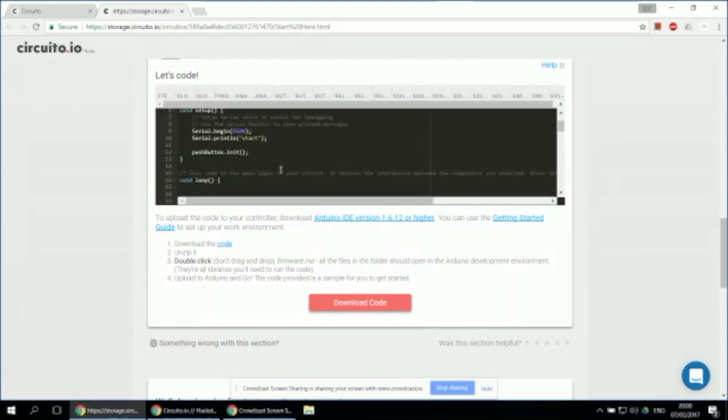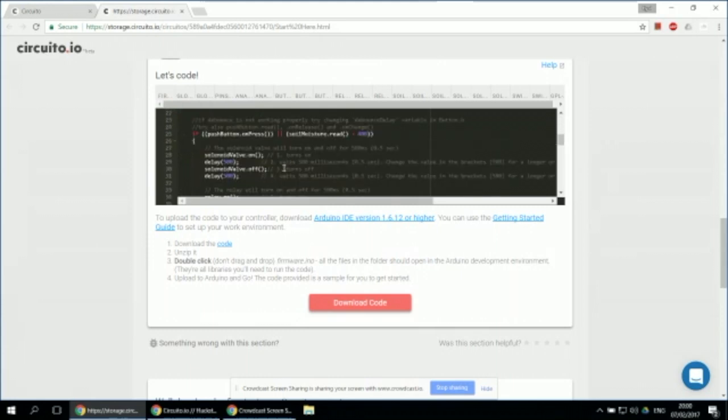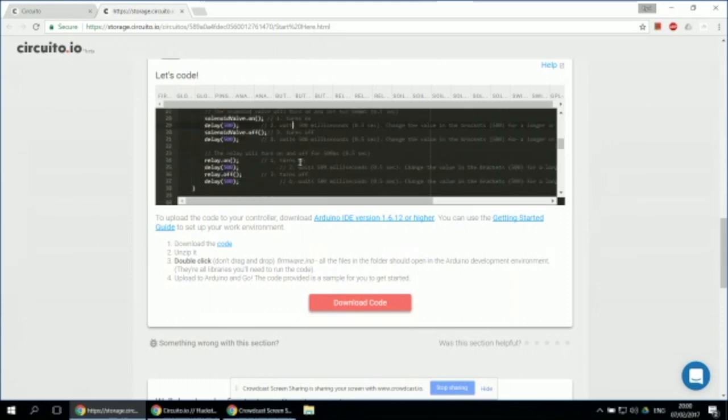And the main logic we provide you with, it's not an irrigation system, but it's an example of how to use all the components you chose. And it allows you to take over from this point and do it quite easily because you choose the push button and the soil moisture. We show you how to read the state and the values and turn the solenoid on and off and turn the relay on and off. So that's a great starting point for the project. Yeah. And it's so heavily commented that even if someone hasn't used these components before, they can really get in here and start tweaking it to make it do what they want.